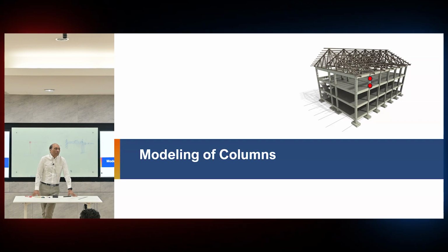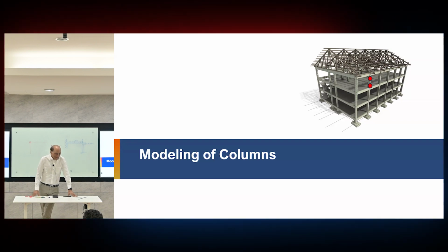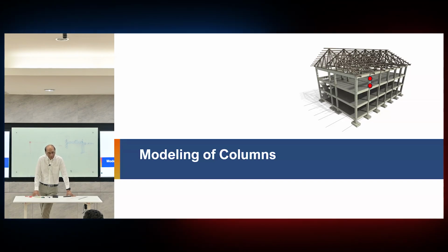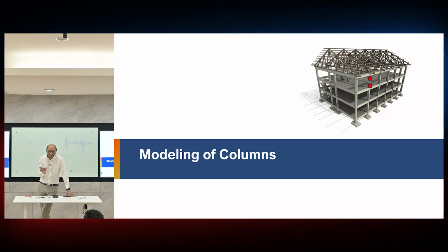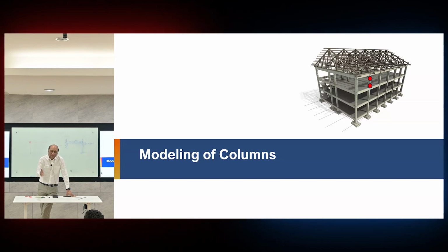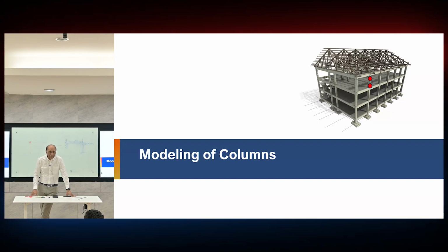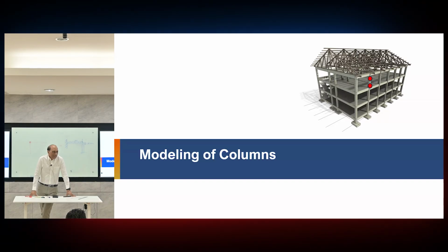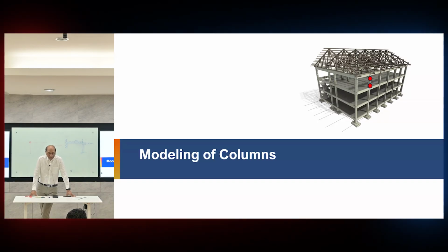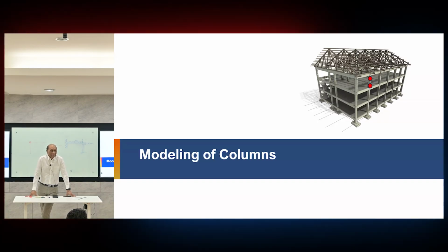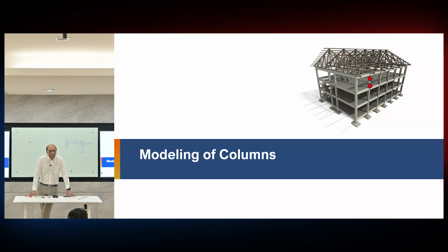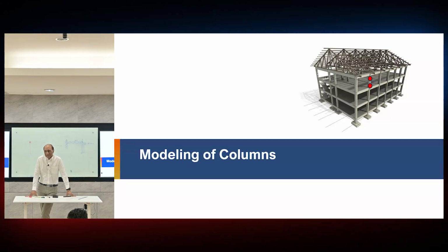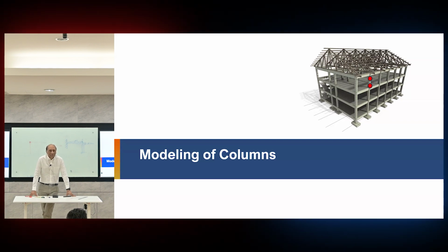So we cannot specify one single hinge there, one single curve. We will have to specify a very large family of moment curvature curves. Not only that, but direction also, because in each direction, moment curvature curve is different. And at each load, it is different. So you will have to input like 100 PMM curves to capture all the behavior for actual loading conditions, which is not practical. Although you can do that in SAP, we have the option, but it's not practical. So that's why we put the fiber hinge.